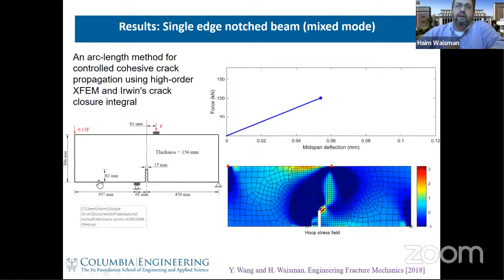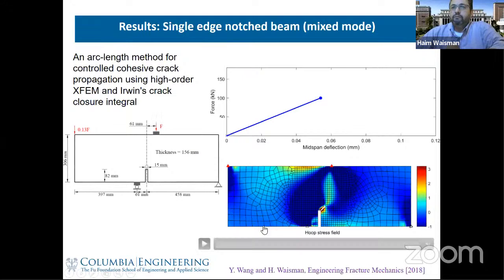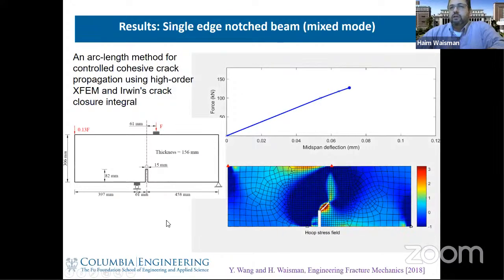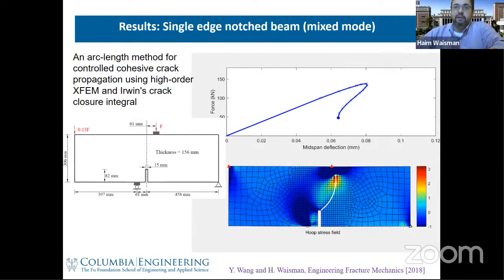So for example, here we have this notched plate problem under loading. This is the XFEM system. And what I'm showing here is the force displacement behavior. As the crack is propagating and you push at this point F, you see an interesting phenomenon. This phenomenon is known as a snapback instability that happens in this type of problem.